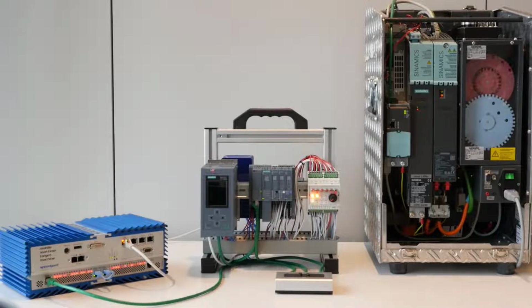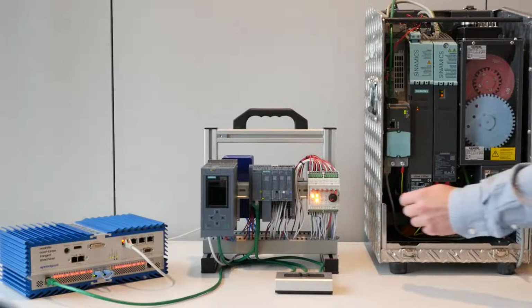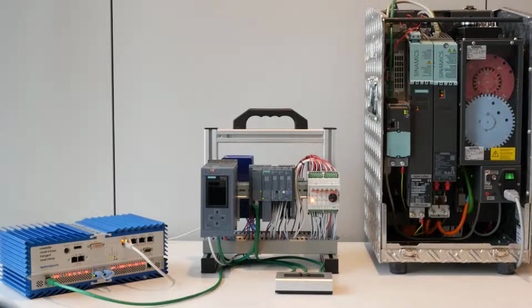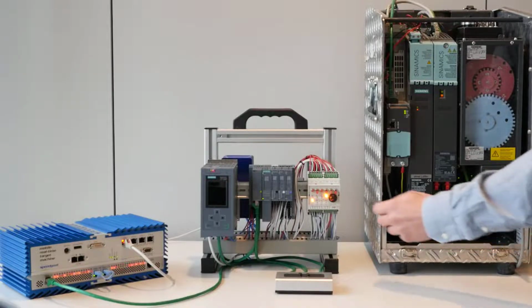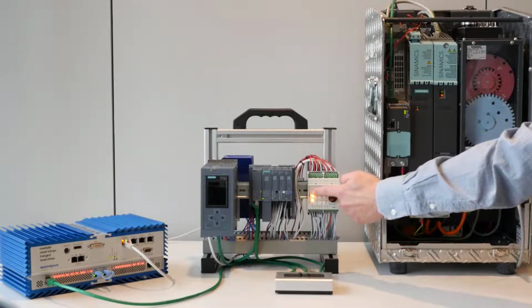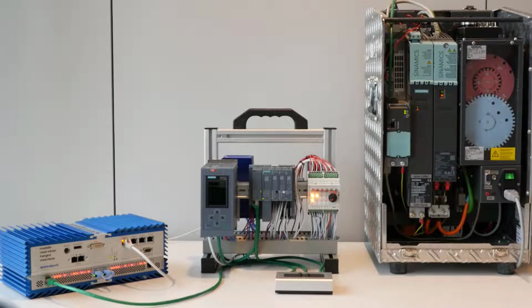In a final on-site commissioning, the commissioning engineers check whether the two motors stop turning when the tank gets empty. They also check whether the system can be recovered by filling the tank and enabling operation again. And they test whether the plant operates correctly at different speeds.